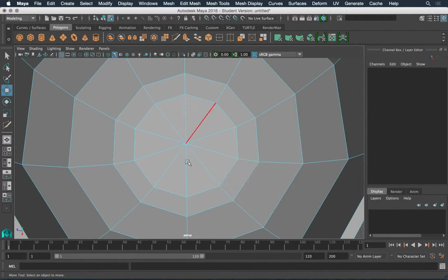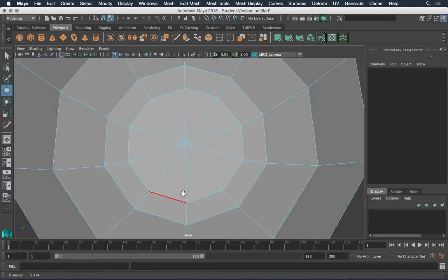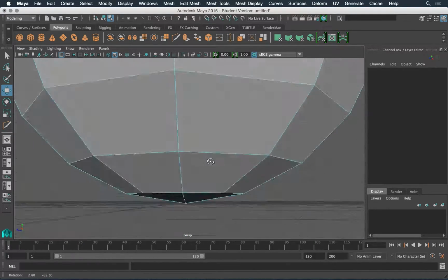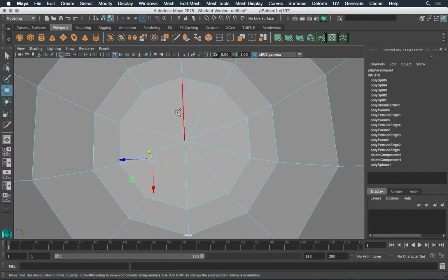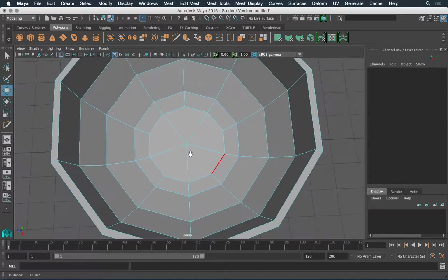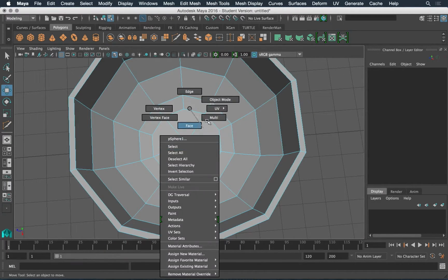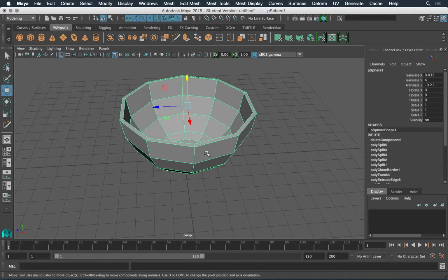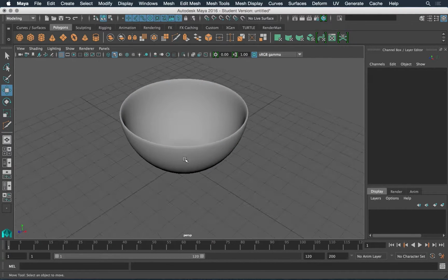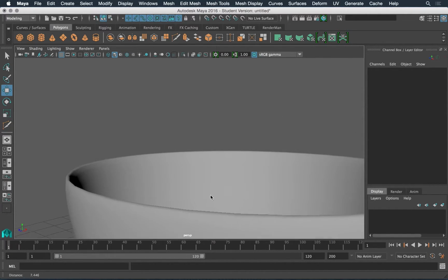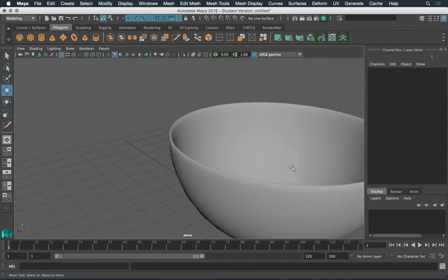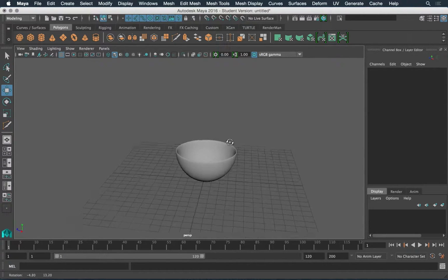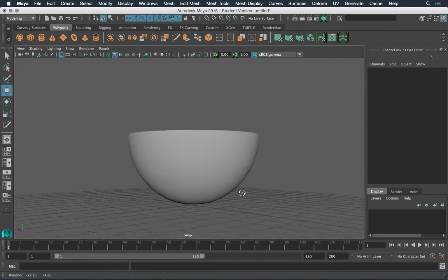Okay, so you're just gonna make that kind of spider web pattern, connect everything to everything. And then, just like on the bottom, I'm going to go in and delete every other. So I'm going to go to Edge Mode, every other, 2, 3, 4, 5, and delete. Perfect. Now if we select the bowl and hit 3, we have a nice solid object with depth here, right? It's not infinitely thin anymore. It's nice and smooth, even though we didn't add too many edges, right?